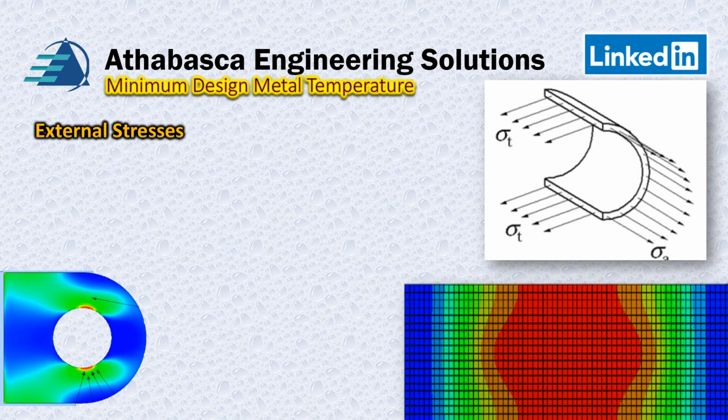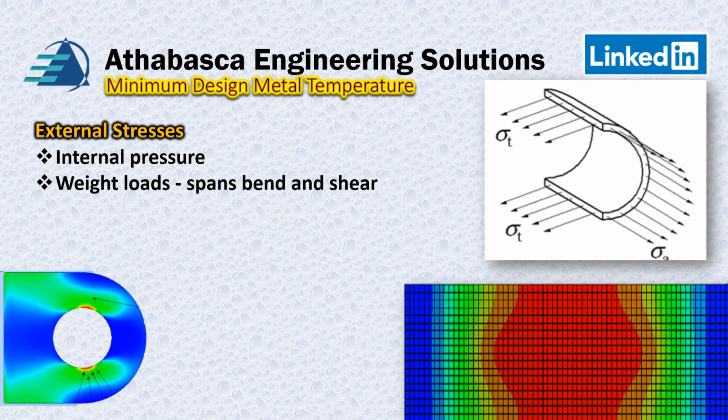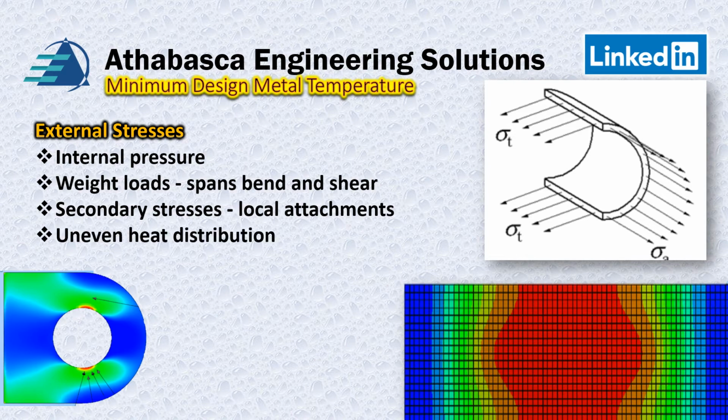Factors that affect MDMT are external stresses, and they can include internal pressure, weight loads and spans, secondary stresses, uneven heat distribution, and even occasional loads. ASME indicates that when one does an MDMT evaluation, they consider all these variables.